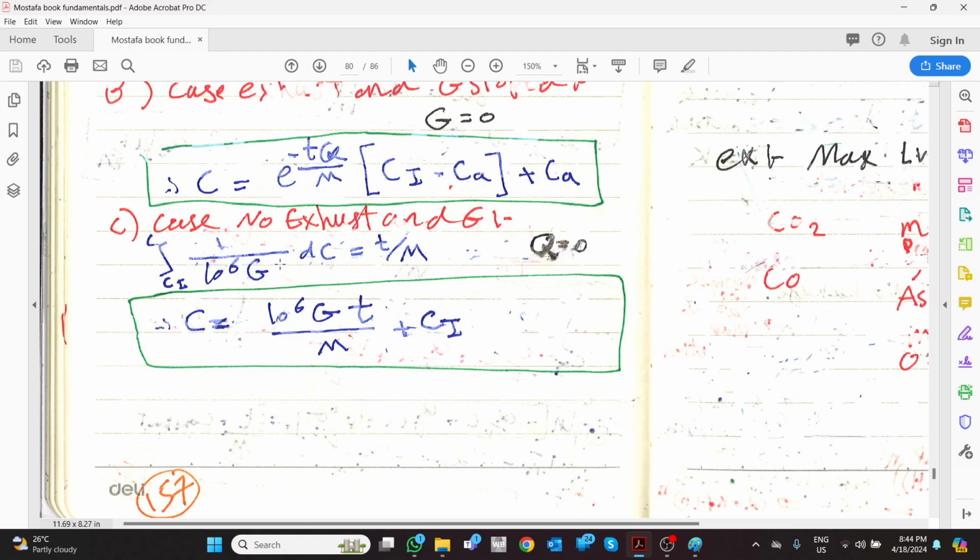So when you make the integration, C equals 10 to the power 6 G times C multiplied by concentration. And by the way, this is logical: the concentration is the initial concentration plus what? A mass ratio, because this is a mass ratio between CO2, for example, and air, divided by mass of air. So it becomes a mass ratio. And remember that G's definition is the ppm per second going to be injected.